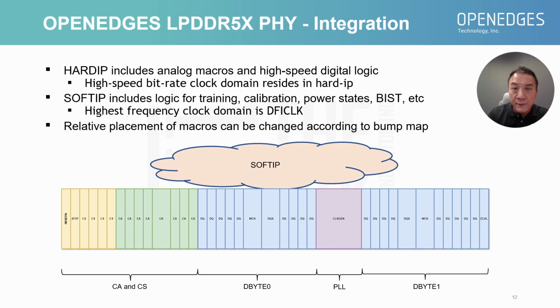What we do is, once we know the relative hard IP signal ordering, we can help our customer with an instantiation depth so that they can read it in and have all hard IPs placed automatically on their SoC floor plan. So this would remove any complications in placements, placement orientations, abutment signals, etc. So essentially, to the customer, once a DEF is read in, the entire hard IP group is placed as if it is a single macro, without the need to fiddle around with the placement further.